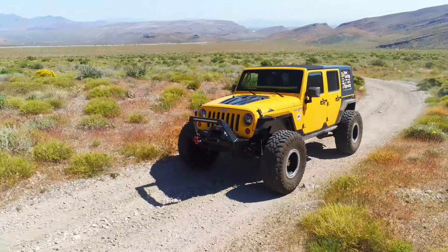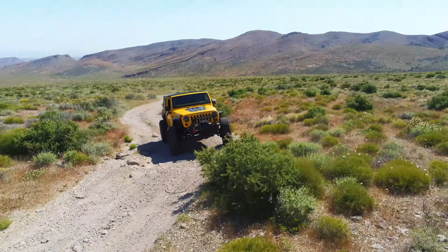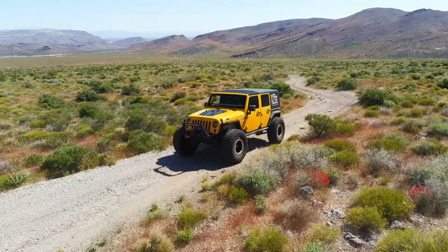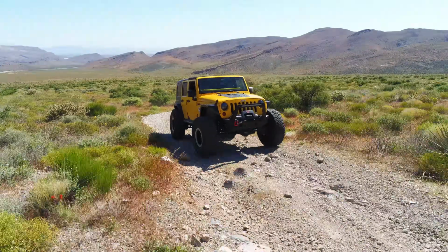One, you're hauling a heavy load. You got a heavy pig of a JK going up a hill at 80 miles an hour. So we need that extra power to do what we want to do. Two is going to be protection. We can't run an engine lean under a heavy load or you're going to start breaking stuff, burning stuff, whatever. So performance enrichment is also a safety mode.